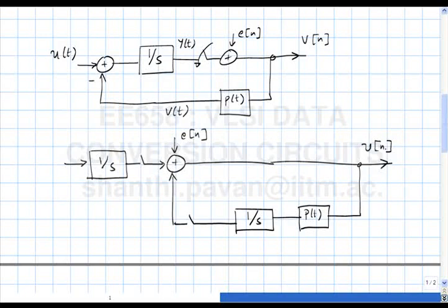Okay, forget about all this. In a first order delta sigma modulator, what is the transfer function from the quantization noise to the output? You are asking the exact expression? Yes, the exact expression. Okay, what does the first order noise transfer function look like? 1 minus Z inverse. This is a first order delta sigma modulator, which means that it implements a first order noise transfer function, which means that the transfer function from E of n to the output V of n will be 1 minus Z inverse, which is the same as 1 by 1 plus L of Z, because L of Z is Z inverse by 1 minus Z inverse. So 1 plus L of Z is whatever, right? The right thing.